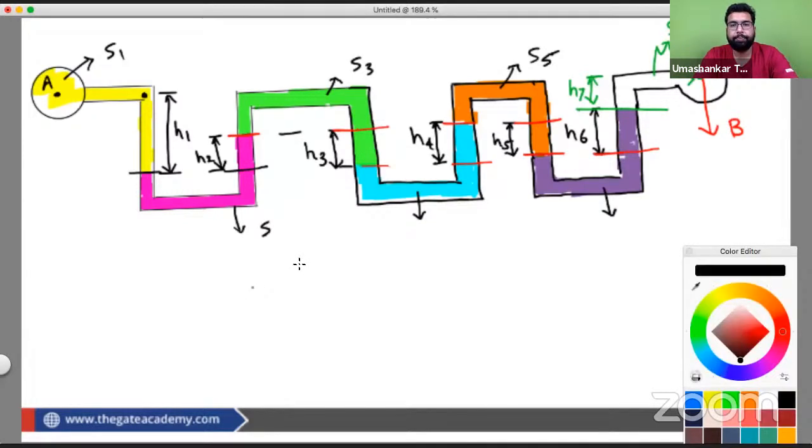Very nice, Prasanna. Okay, so I'll do it now. So we have two pipes. Again, we can start either way from A to B. From A, what is our concept? We need to change everything to water. Whatever pressure is there inside this pipe, we are not at all worried about it. We can start by writing HAW. From this point to this point, we need not write anything because we are not changing in the horizontal direction, so the pressure is not getting changed.